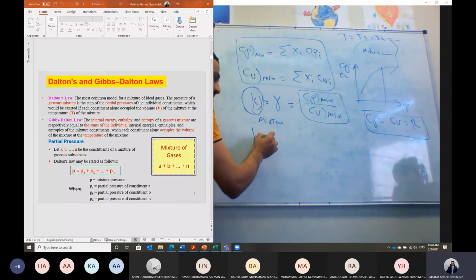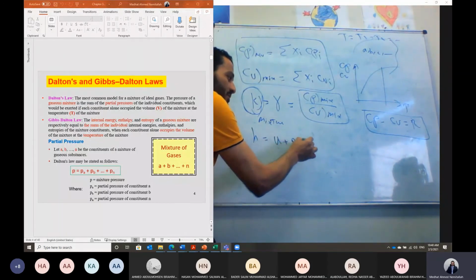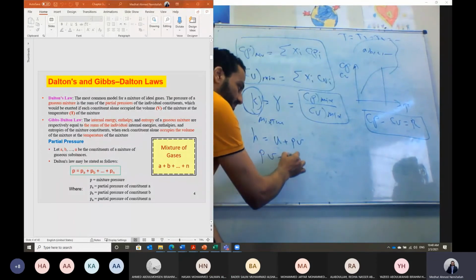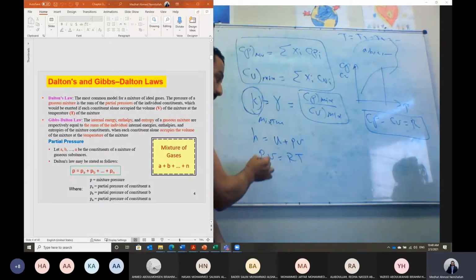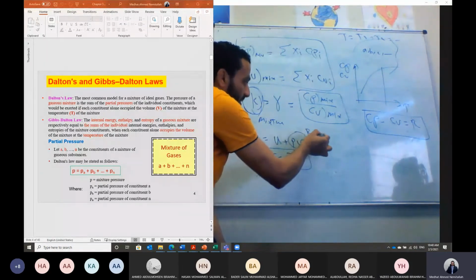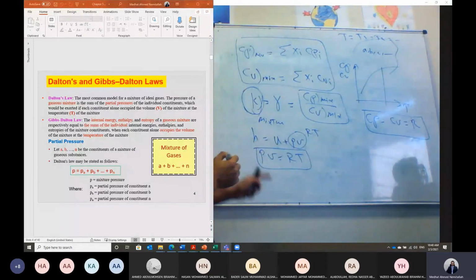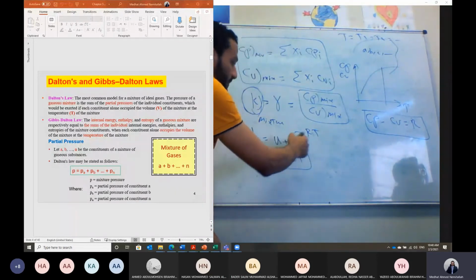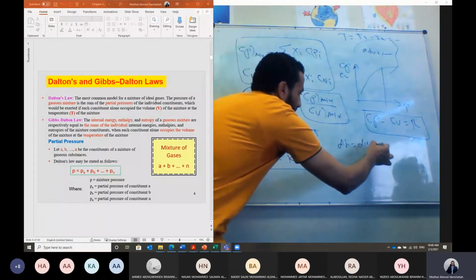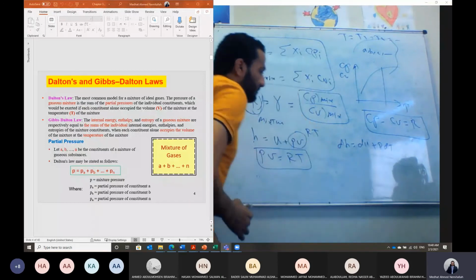I think you know. Enthalpy is the internal energy plus flow energy. And for an ideal gas, we have pressure multiplied by specific volume equal to RT. You know about this equation, PV equals RT? Yes, the ideal gas law. Then we can just replace PV by RT. So the enthalpy will equal the internal energy plus RT. Just differentiate, so dh will equal du plus R dT.